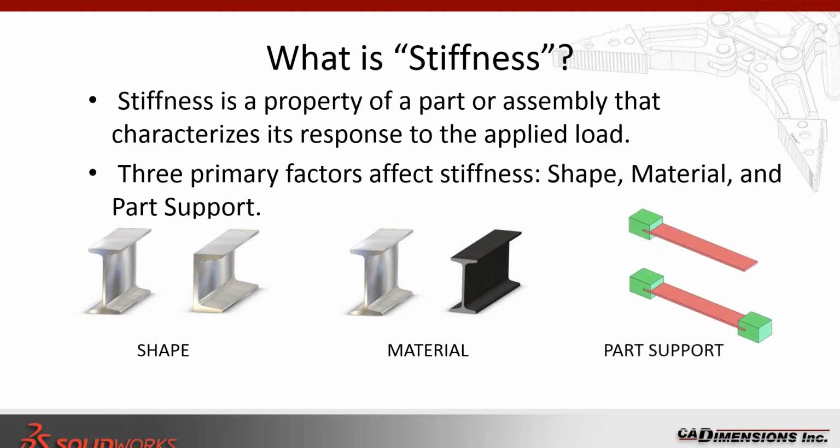So if you're not dealing with just parts, if you're dealing with now assemblies, you have to consider all the different parts being mated together. And when all these different parts are mated together, they are reacting to different stiffness of each part. Now, if every part has the same material, then maybe you might be able to get away with that. But now if you're dealing with different material, different stiffness, and these parts are touching each other, moving, and reacting to each other, then you need to consider nonlinear analysis.